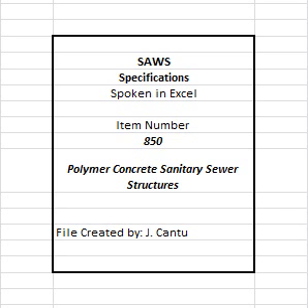C. In no cases shall the wall thickness be less than manufacturer recommended thicknesses. D. Design wall sections for depth and loading conditions with wall thickness as designed by polymer concrete manufacturer. E. Polymer structures will be designed based upon live and dead load criteria in ASTM C857 and ACI 350. F. Polymer concrete structures shall be designed by manufacturer to meet loading requirements. 18. Structures shall be designed with sufficient bottom anchorage and side friction to resist buoyancy. 19. Field cast flotation collars are acceptable. 20. Joints shall meet the requirements of ASTM C443.